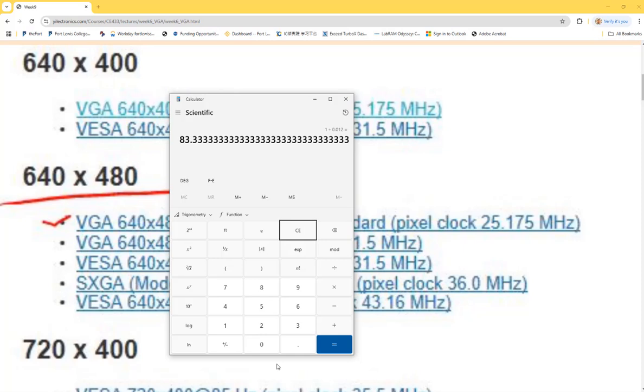So 83 hertz. Are we getting the point here? Everyone? So that means for a 640 by 480 picture, this many pixels, it takes about 0.012 seconds to finish the assignment of the pixels for that picture, which is probably giving you 83 hertz.